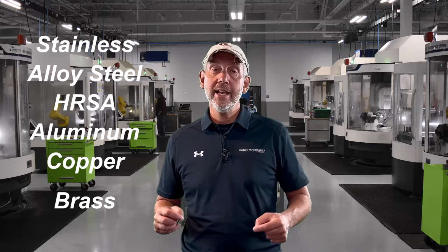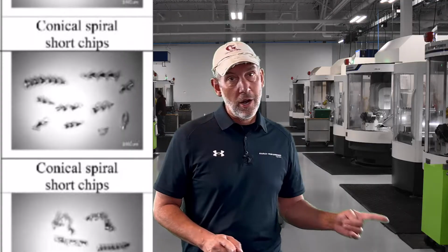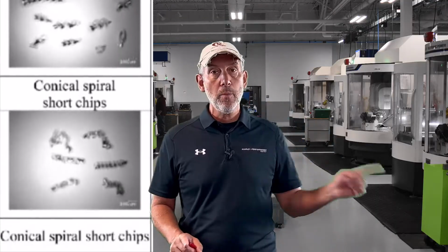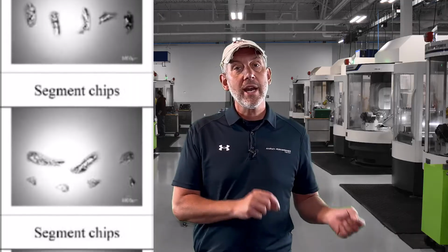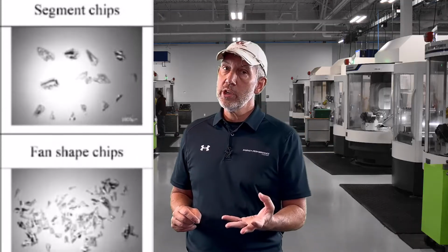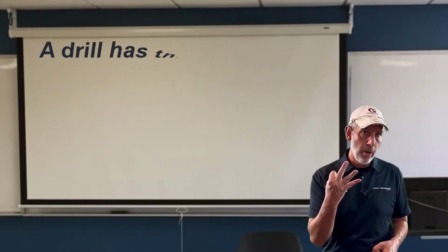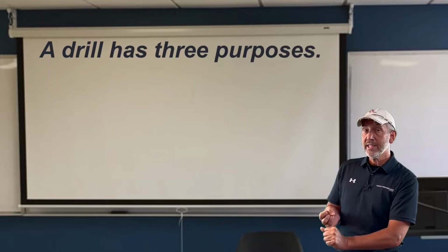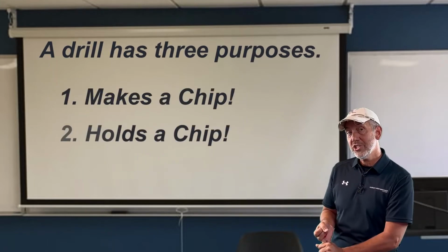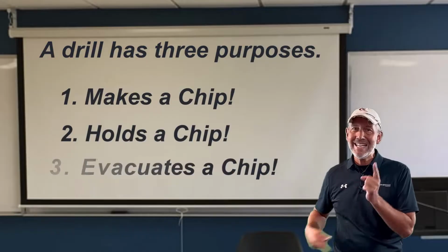Or what I mean is they have different characteristics for the chip, which means some are stringy, some are gummy, some are hard, some break, some don't break. So we have to accommodate that, because a drill really serves three purposes. It makes a chip, it holds a chip, and it gets rid of a chip.